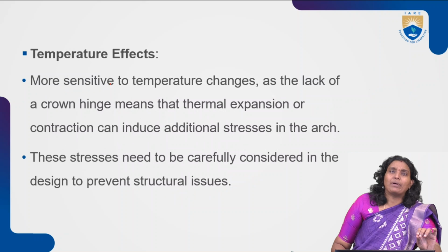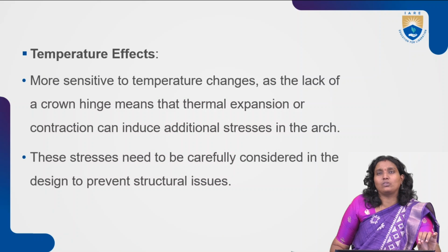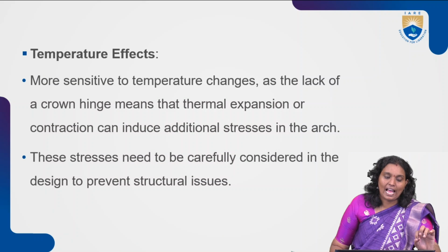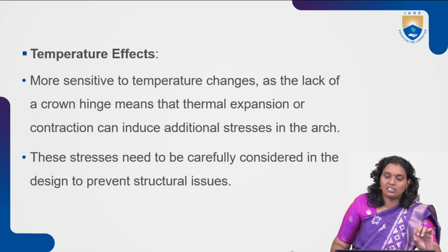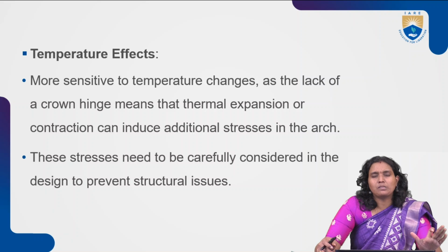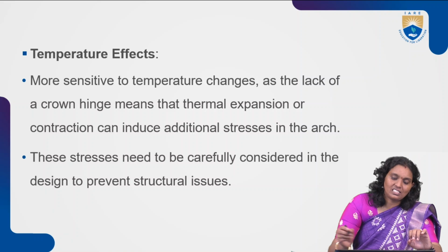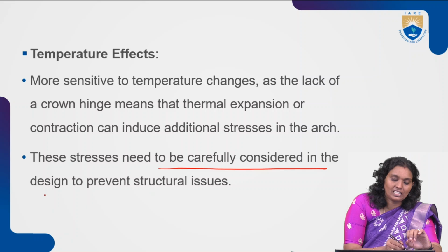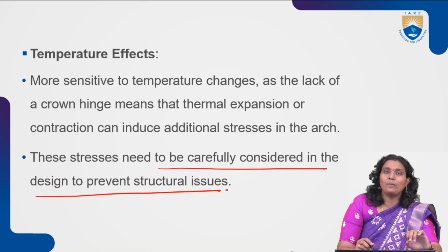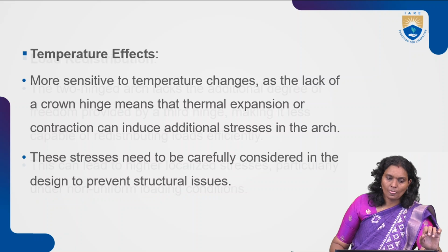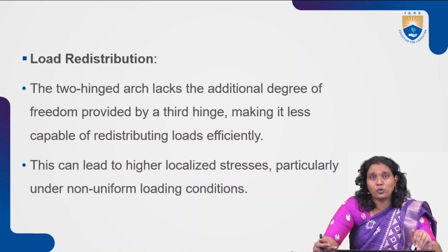And in temperature effects, it is more sensitive to temperature changes, as the lack of the crown hinge means that thermal expansion or contraction can induce additional stresses in the arch. These stresses need to be carefully considered in the design to prevent structural issues. And also the load distribution.